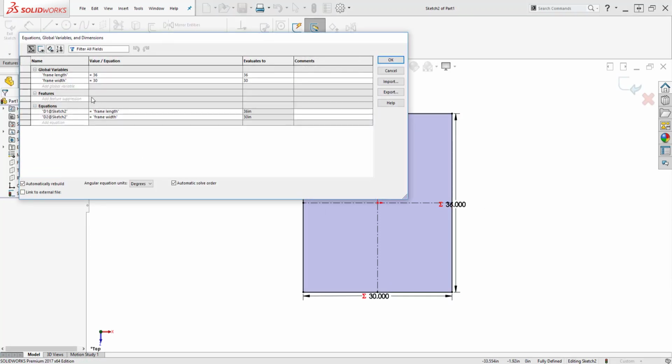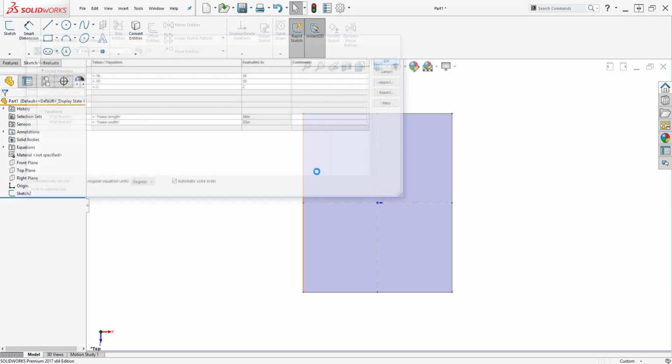Using an extrude, I'm going to do the same for the height variable, which is equal to my tubing height of 2 inches since we're using that 2x1 tubing. This is going to be a dummy solid for when we create the frame, and the frame is going to be based on these parameters we just set up.